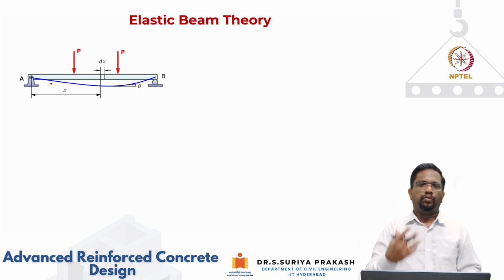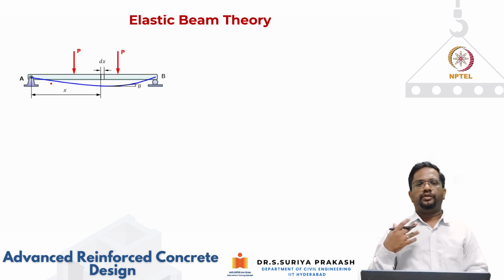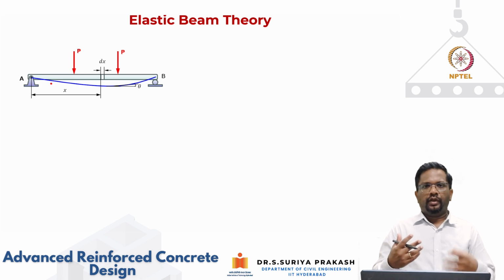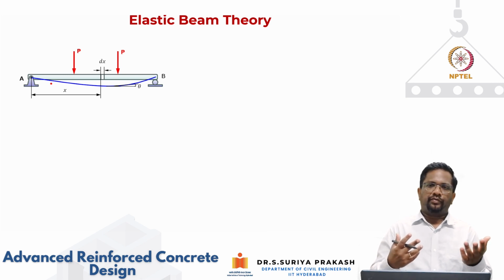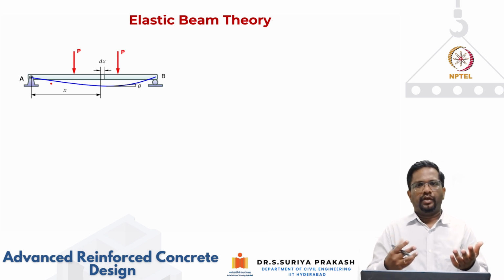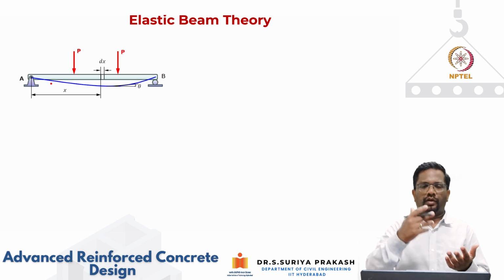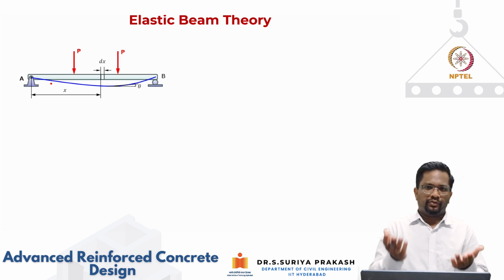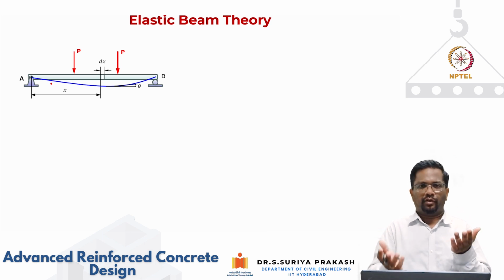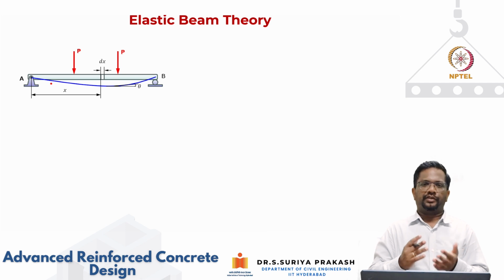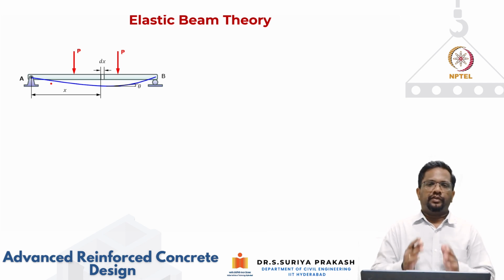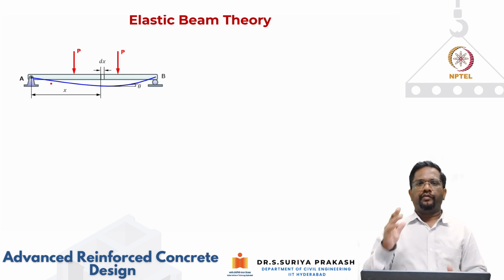I kept talking about moment curvature analysis. Why do we need to do moment curvature analysis? It gives us an idea if I want to compare the performance of a particular beam with different amounts of steel, or if I want to change the strength of the concrete, how much strength is increasing and how much rotation capacity that particular section has. For that, in a normalized way, if you do moment curvature analysis, we can get a very good idea how